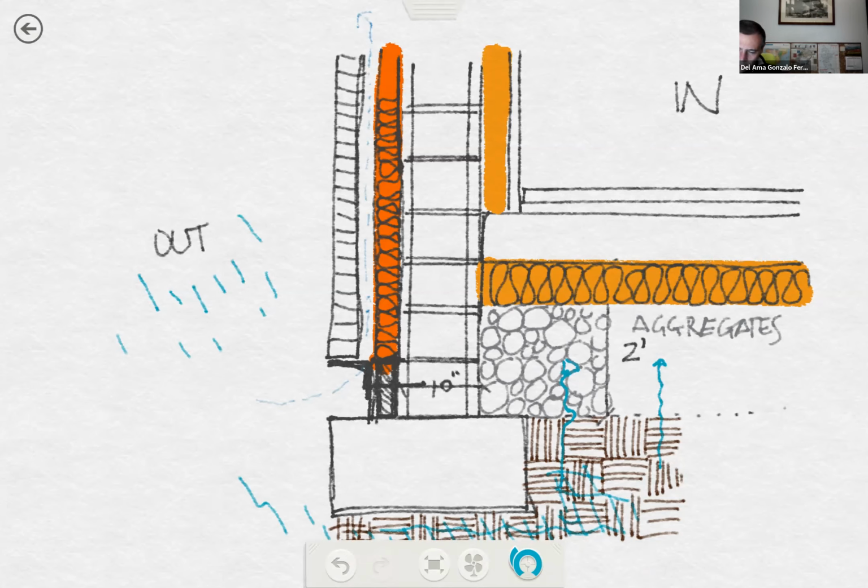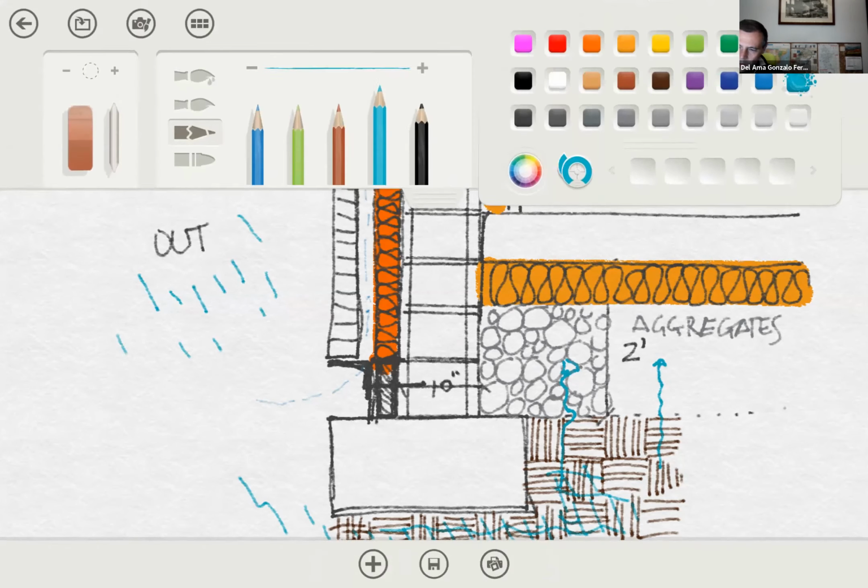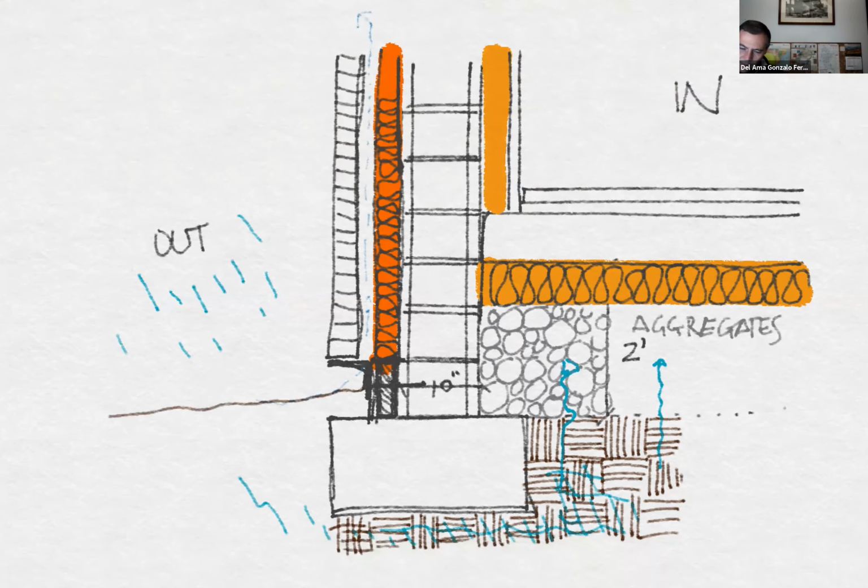But yeah, we need the soil somewhere, so we can have the soil here. Okay, just sloping out so that if it rains, at least we are not forcing the water to get into the building. Okay, so this is the compact soil as well.